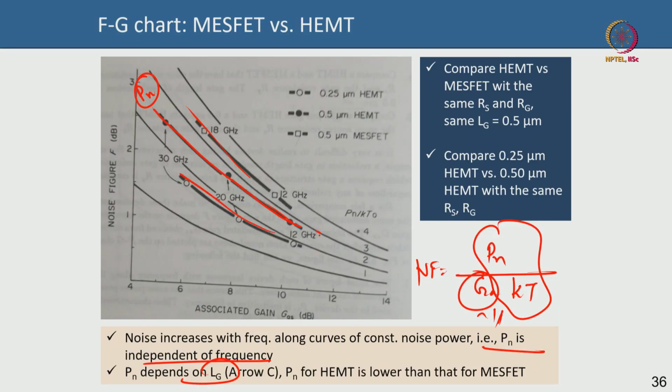Okay. So, with that we come to a conclusion of this lecture 24, which also brings us to a conclusion of the discussion on AlGaAs GaAs HEMT. We discussed a little bit about noise performance, we discussed power performance in terms of the critical device parameters: contact resistance, breakdown, gate leakage, transconductance, etc. So, we know what a HEMT is and how it works, but there are still many things about HEMTs.